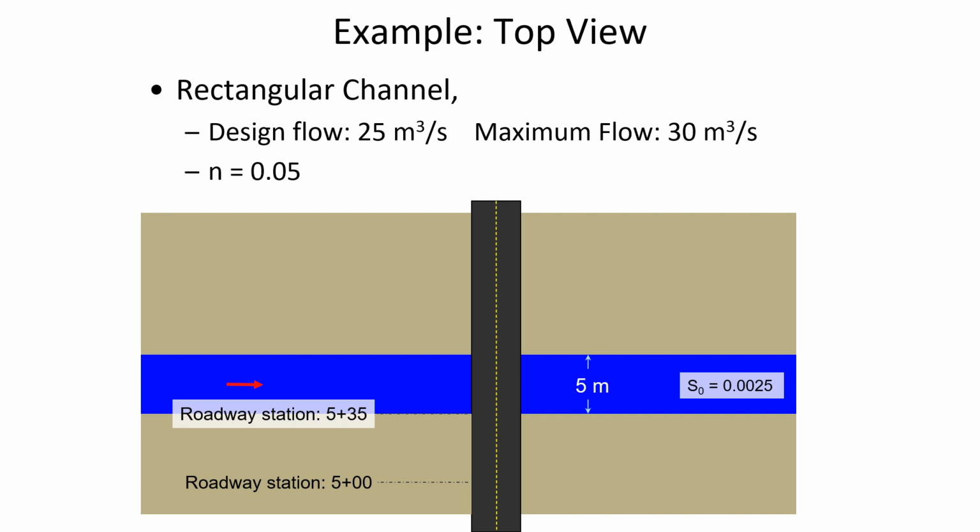But it acts as a weir, either a broad-crested weir or a sharp-crested weir, depending on how wide the road is. So when it asks for the crest length, it's basically asking how long the road is from here to there when the water level has risen enough that it's about to flow over the top.